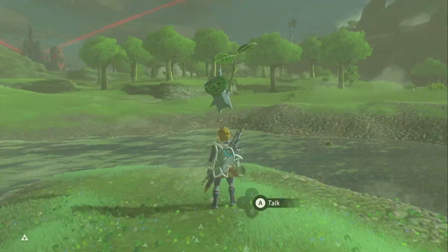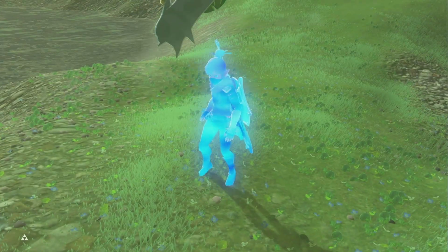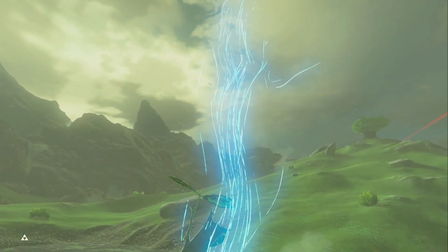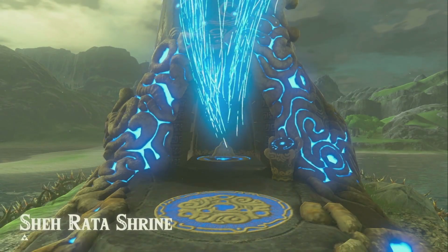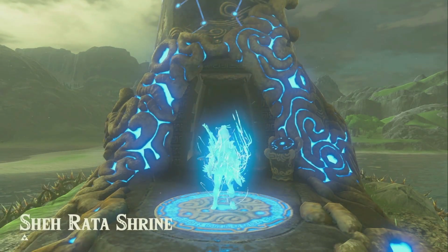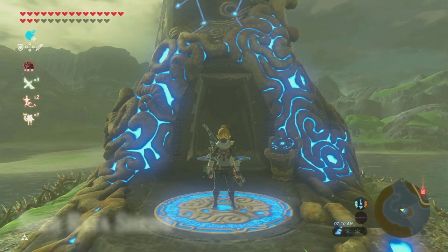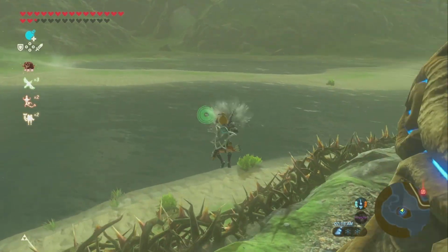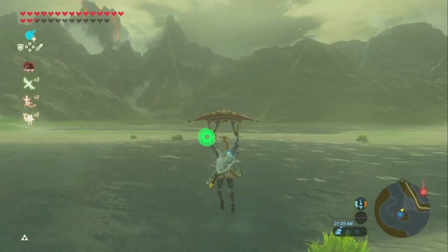Strategy. If the water pressure is low for no apparent reason, you might recommend flushing of the water heater through the drain valve. Attaching a hose to the drain and directing it over to a floor drain or outside the building is fairly straightforward. Most people recommend shutting off the heating supply and opening the drain valve until water runs clear.